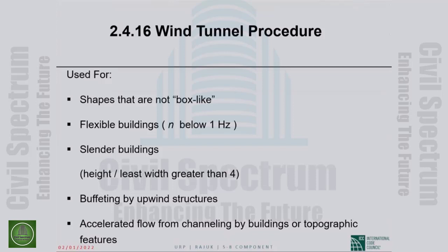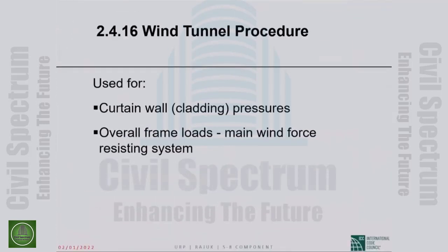That happens. A narrow gorge could be between two tall buildings, or between a building and a hill, and you may end up with higher wind. If wind has to pass through a narrow passage, the velocity will go up. And if your building is right at the end of that passage, then you may be looking at problems.